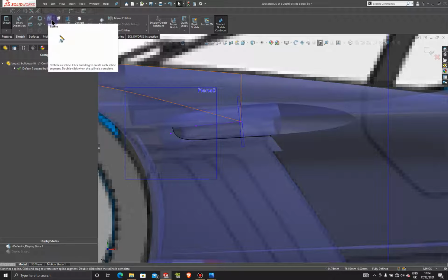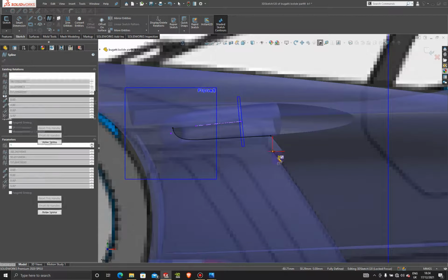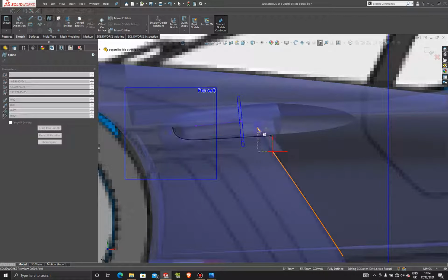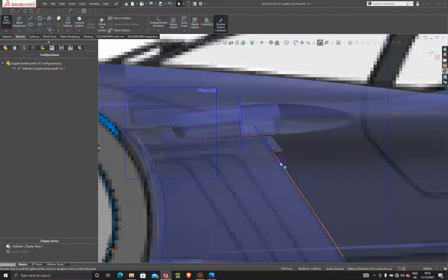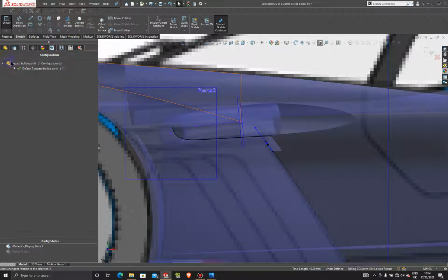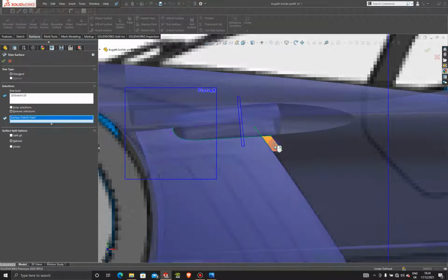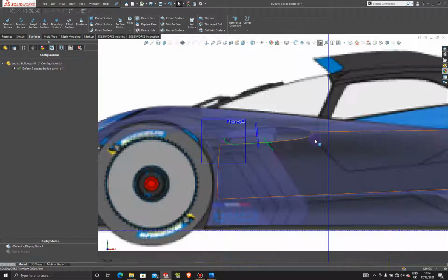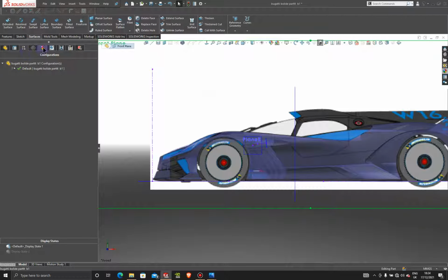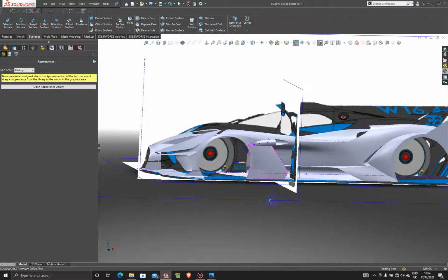So what I'm going to do is grab a spline here, and I'm going to come from this edge here and then all the way through out here, right? Exit the sketch. And I want to use this edge here as this edge, hold control with this line. I want to add tangency with this one. Okay, and if I go to surfaces and trim surface, I'm going to get rid of this small piece here. Okay, so now if we take off our glass appearance here, remove the appearance, I can see things are all starting to look a lot better.